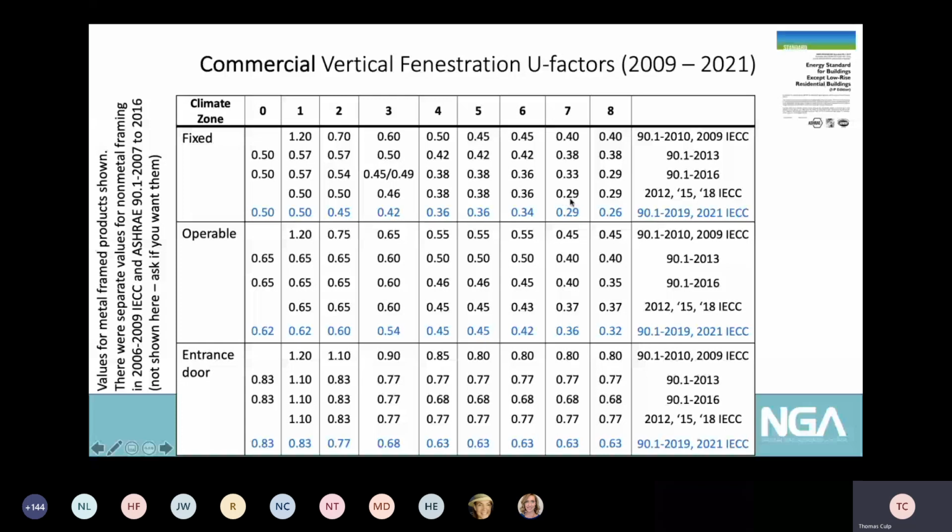In 2016, you were just kind of notching with the technology. So in 2016, you could use a 3.8 up through zones 4 and 5, and then you jump to a 3.6 in zone 6. Now that 3.6 has moved down to zones 4 and 5 in the 2019. In some of these lower numbers like 3.3s and 3.4s, they have jumped from zone 7 back to zone 6 now, and then we're having kind of 2.9s and up in zone 7, and then zone 8 is making another step. So the exact numbers aren't exact, but when you look at the actual technologies that are used, I could jump ahead to that. Maybe I'll do that at the very end.